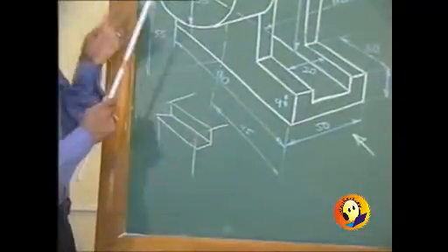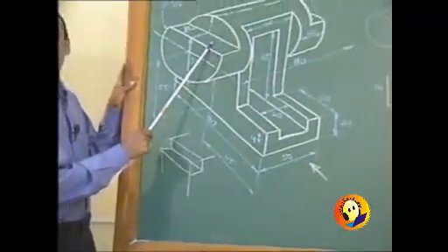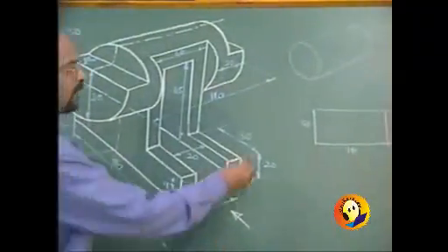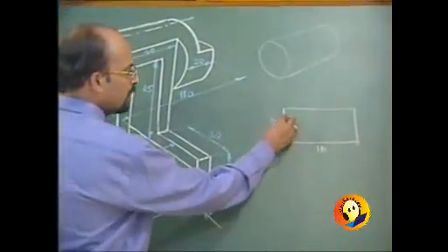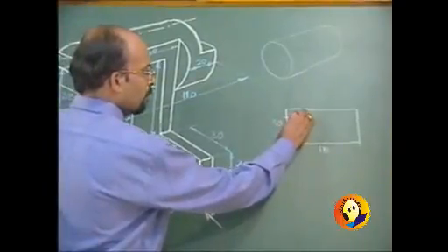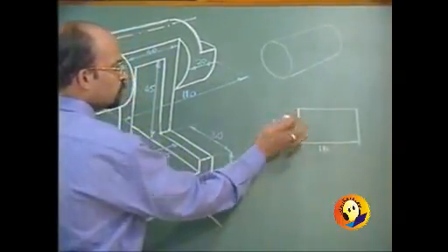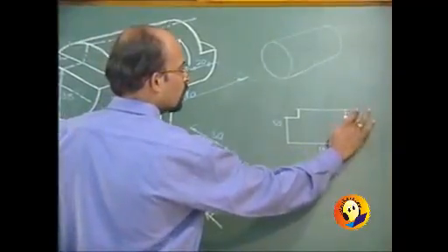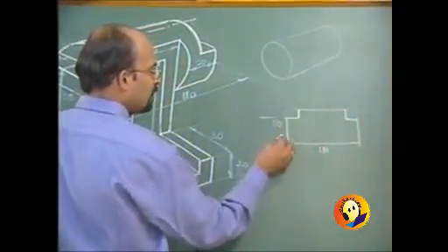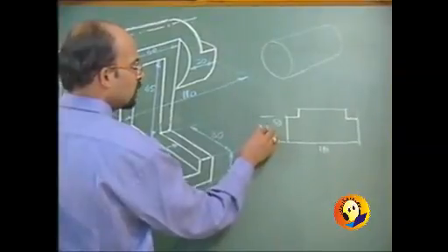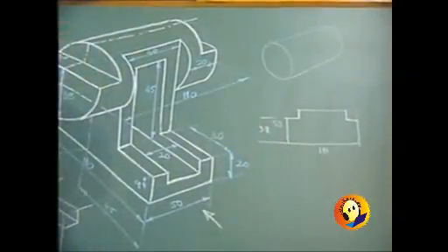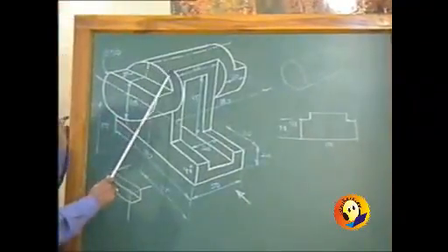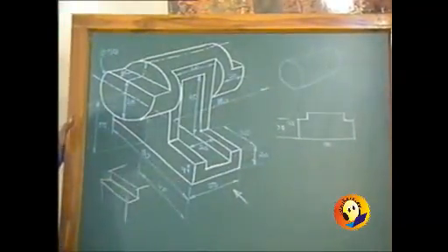A similar step you can see over here, and that means in the front view I will have to measure a distance of 38 and a depth of 10 and chop off this portion. Similarly on the other side. And to mark that, I can very well say that this 38 was given to me. So far as the cylinder is concerned, it can be shown like this.